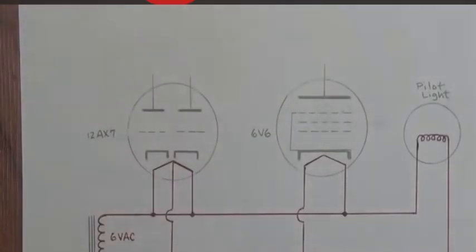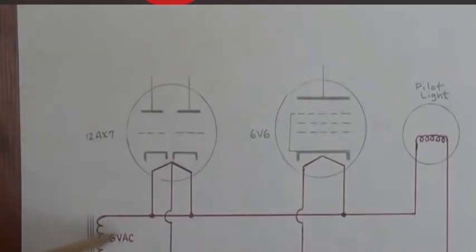Okay, let's take a look at the first of the little bite-sized pieces. The first will be here the 6 volt AC circuit. Now this is on the right side, this is the secondary side of the transformer. Now over here on the left side, we have the 120 volt winding that we plugged into the wall. The reason that we have 120 volts over here, and it turns into only 6 down here, is that for every one winding we have in this coil, we have 20 windings over here. So there's 20 times as many coils on the left as there are on the right.